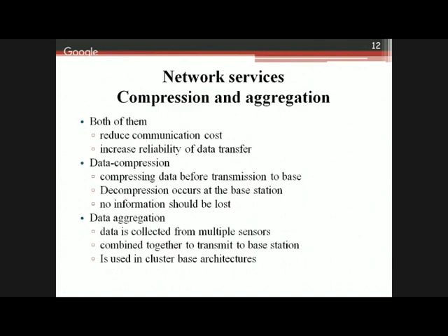So it's very important that we can find the redundancy in data. Why should we waste our resources or power on redundant data, the same data? So it's very important how we can distinguish the redundant data from our useful data. That's where the concepts of digital signal processing come into the picture. One example is the autocorrelation function, which can give you the similarities or patterns among the data. Once you see the patterns among your data, then it's quite easy to compress it by using mathematical operations like mean, variance, or the Fourier transform, wavelet transform.